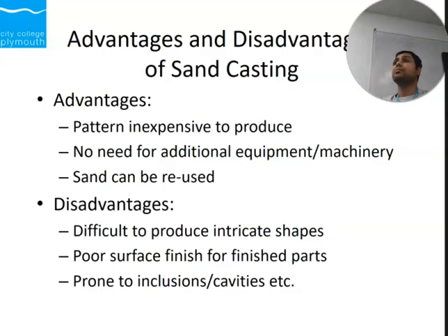Sometimes inclusions, when you're pouring it in, what actually happens? The sand particles can go into the casting, and that sand particle will act as a stress riser, which can cause some kind of degradation in the tensile strength, mechanical properties, and so on. Sometimes air bubbles can go in and cause cavitation, which can result in stress risers as well. Okay.